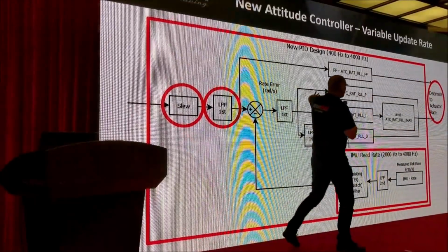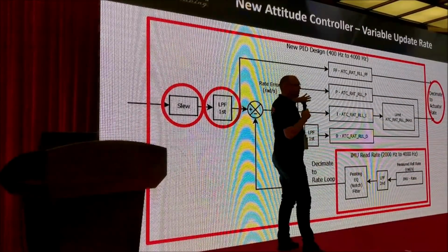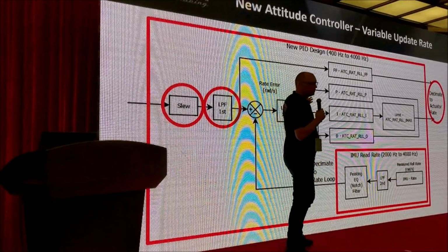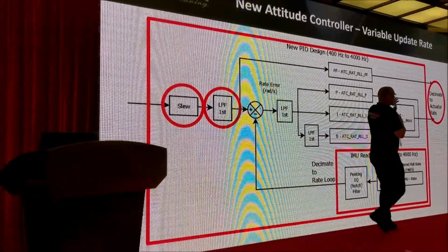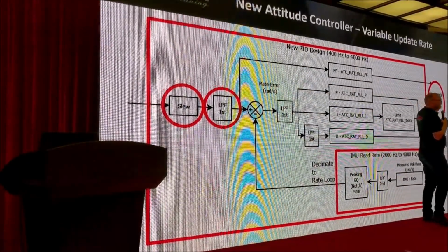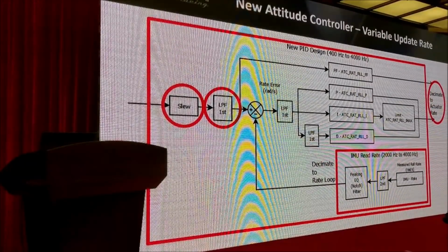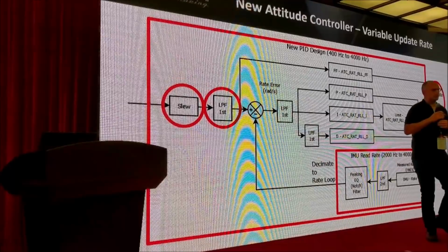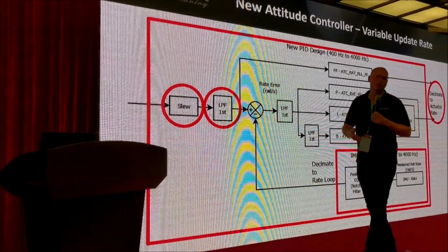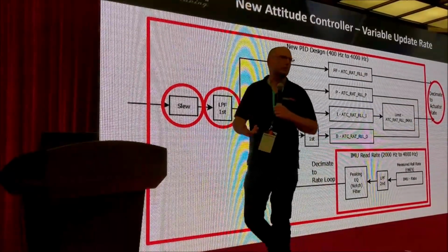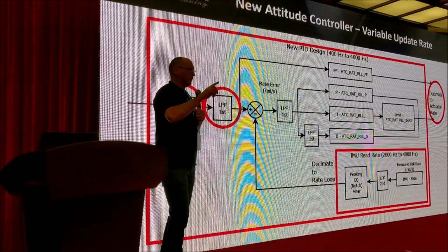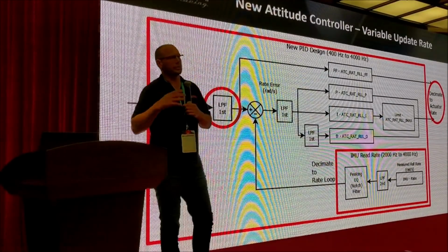So by running this at 400 Hertz in plane, for example, and then outputting only at 50 Hertz, we're able to keep those noise signals out of the servos and make planes much more robust to engine noise, for petrol-driven engines and that sort of thing.